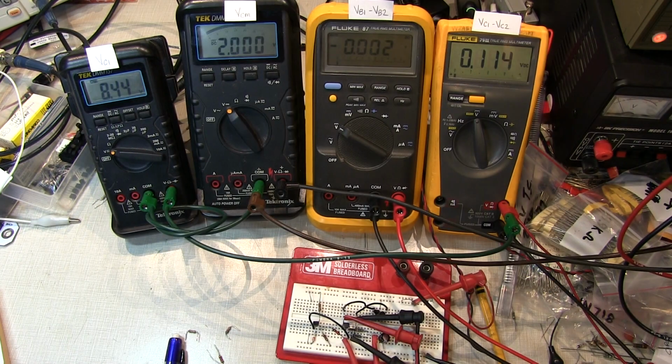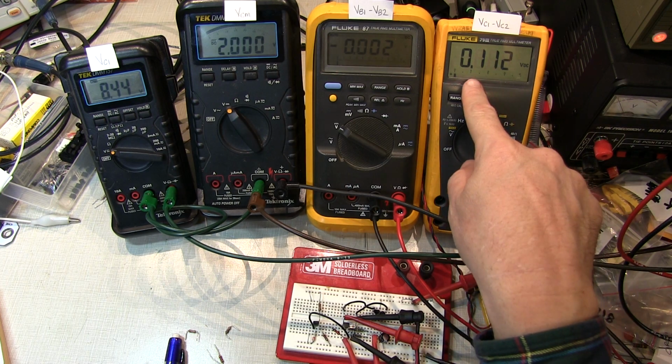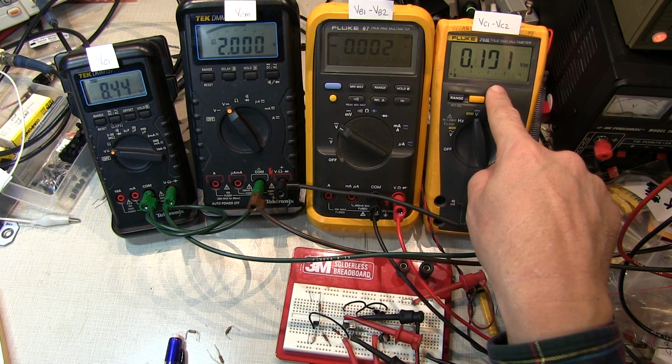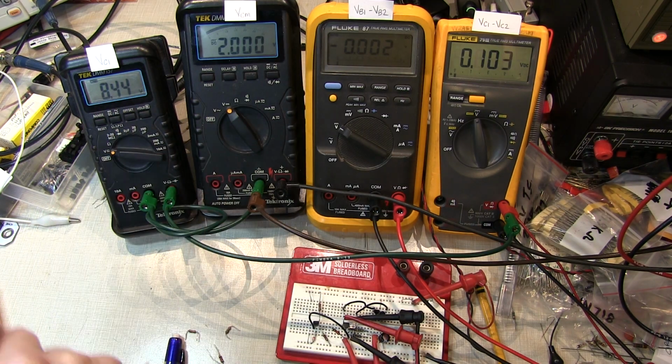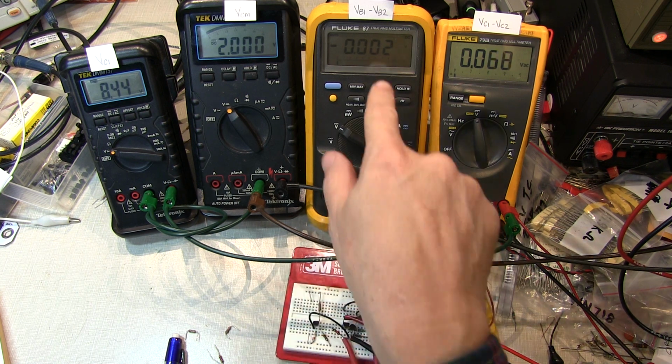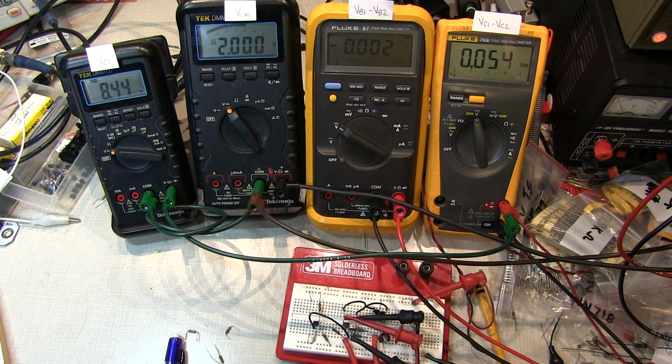Okay, so I've got this set up here now. I connected the output of my differential amplifier to the little current mirror that I had from the previous set of videos. We're still looking at the output voltage difference between the two collectors. The collector of C1 is sitting just about a diode drop below the power supply here, and we're still looking at that little bit of input voltage difference. I've got the common mode still set to 2 volts.